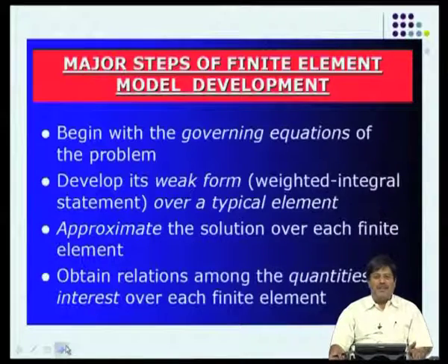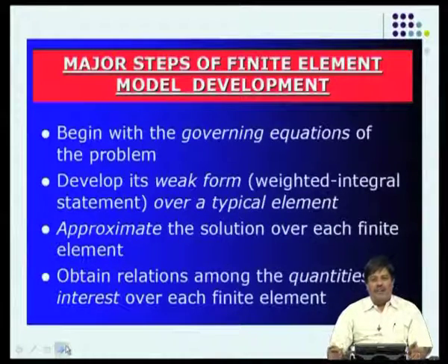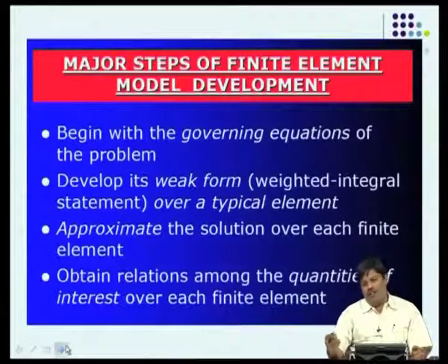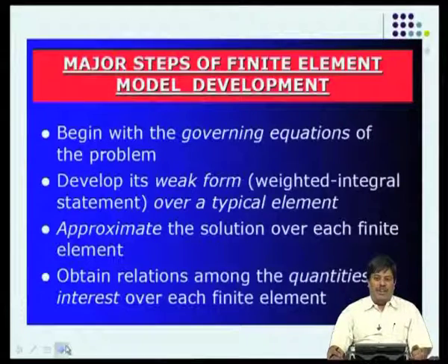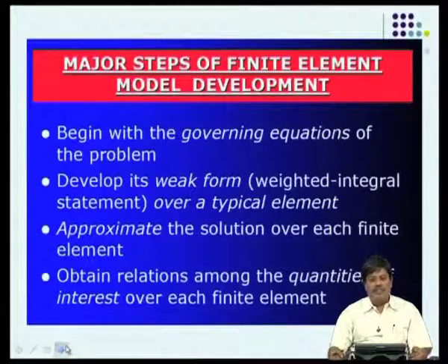So, the major steps in finite element model development: we begin with the governing equation of the problem, and the problem is converted into a weak form of the governing equation, which is an alternate statement of the equilibrium. We can use a weighted residual statement or weighted integral statement for developing this. We find the approximate solution, and obtain the relations among the various quantities of interest over each element.